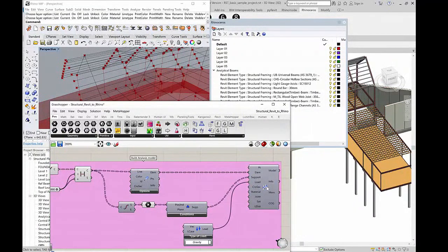What's interesting too is that once I get this information back out, the actual results of the calculation, we could technically push the results back onto the Revit objects through parameters using Grasshopper, all within the same definition. And so you can see how we can push and pull and grab information and really manipulate it in Grasshopper and then push it back to wherever we need to store that information. For instance, back on the Revit model, if we're going to send that back out as the results of our analysis, or maybe in a report or Excel spreadsheet or something like that. So without actually having to bake it ever in Rhino.